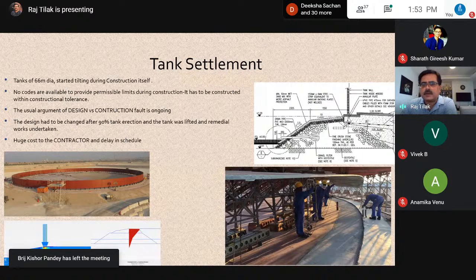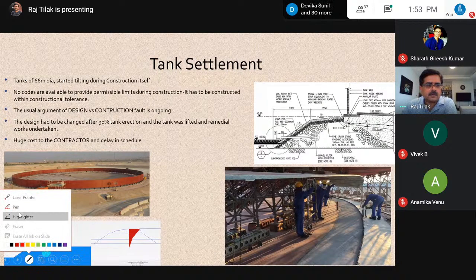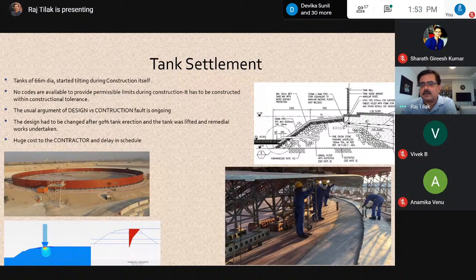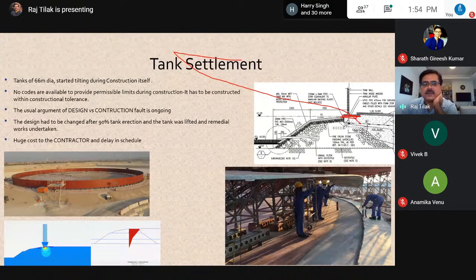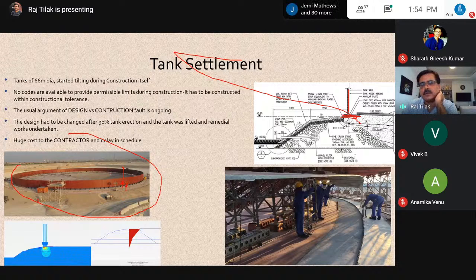But you see there is a kind of a horizontal plate. This plate is called the annular plate, and this is placed first, as you see from this picture here, and over which you erect the tank. First course, and then you raise this up, and then you put another layer from the bottom. So the next layer will come from the bottom. It keeps on coming this way, and then the tank goes up.